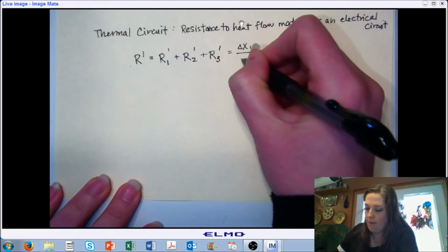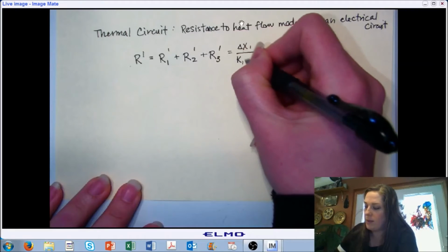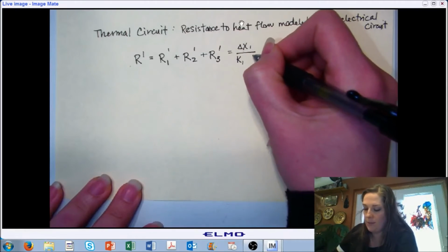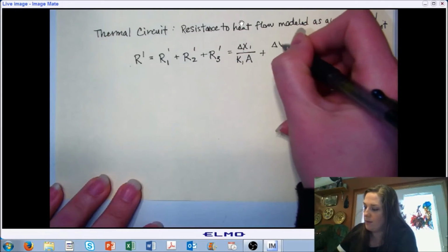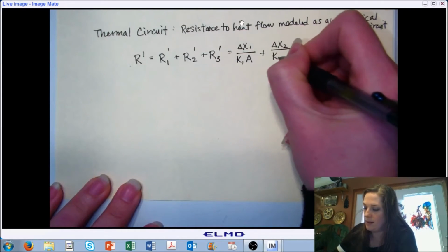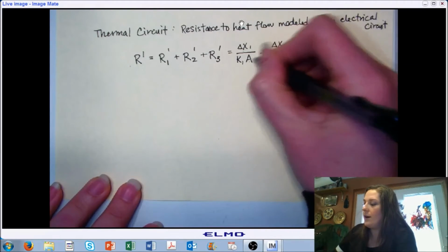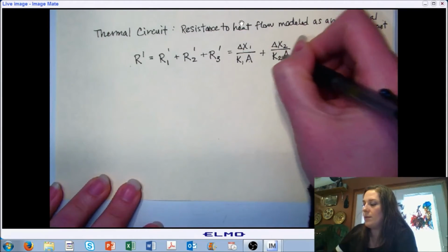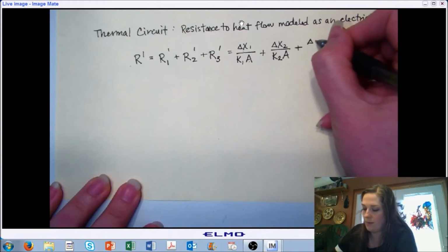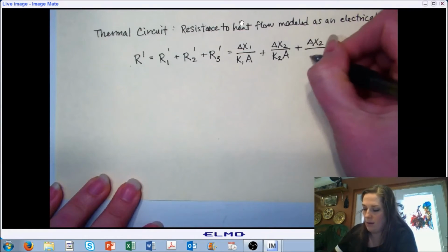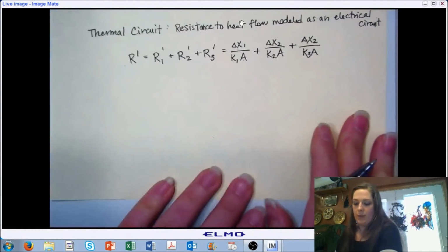So where we have some wall depth with some material that has a resistivity, and another piece of wall that has another resistance. Your areas do have to match, but your wall depths and your materials don't have to match in terms of this combination. In terms of the way I'm writing this equation for the combination.